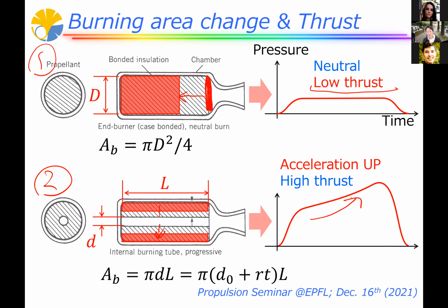And this is quite bad for propulsion, especially for a launch vehicle, because the launch vehicle is losing its weight by combustion. So combining with this solid propellant, pressure is increasing and the weight of the rocket is decreasing. And this means the acceleration is increasing very much. So this is not so preferred.